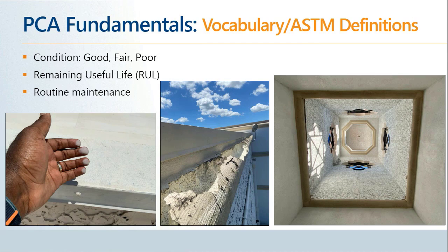Another item that is mentioned is RUL, which is remaining useful life. It is important in evaluating the repairs that are likely required. RUL considers generally accepted service terms for the materials and systems, the observer's experience and observations. RUL is more applicable to systems with more defined service terms and fewer variables, such as mechanical equipment in a specific installation or control environment, but it's also used for sealant and roofing materials. The RUL is often used as a guide along with the conditions observed in the field.